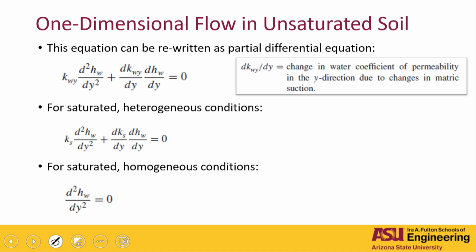Let's say, for example, a saturated case. So this is the general equation, but you have an unsaturated or heterogeneous condition. For a saturated condition, that permeability becomes a constant, right? It's K sat. Oops. That Ksat right here, right? And basically, this one also becomes a constant, and this is your Ksat. And we leave it like that because it's heterogeneous.